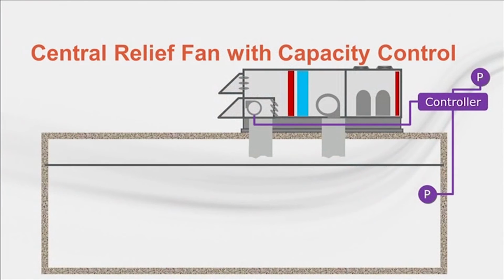Sometimes this is called direct pressurization control. This is common with a VEV system or if demand-controlled ventilation is used. With the addition of a variable speed drive, a pressure sensor, and controls, a relief fan can directly respond to pressure changes caused by the system and building, which results in more stable, occupied space pressure. This type of control is more flexible than simple on-off control because the fan can be placed anywhere along the return air path and the set point can be adjusted.